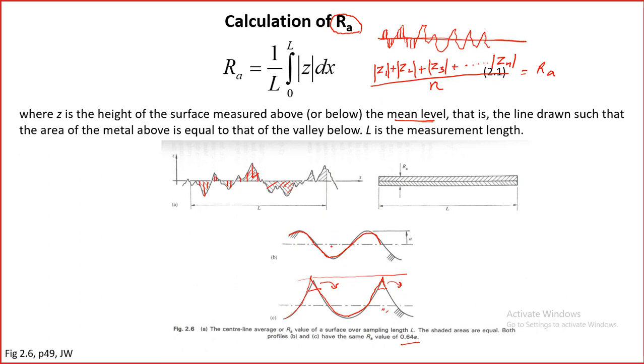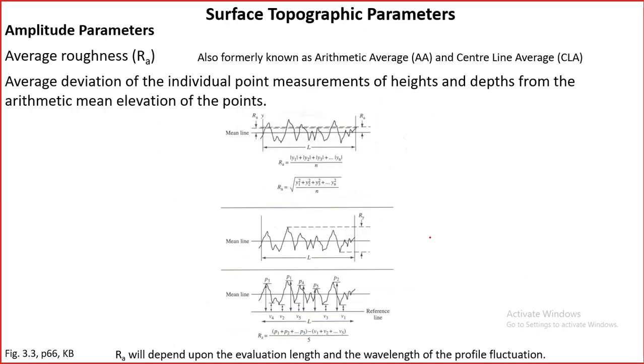Even for the lubricated case, for example if the lubricant is here, this area may act as a constraint for the movement of the liquid. Therefore some hydrodynamic pressure can be created in a localized way. So this can help in the lubrication process. So this is the issue: the actual surface profile must be considered, not just Ra.